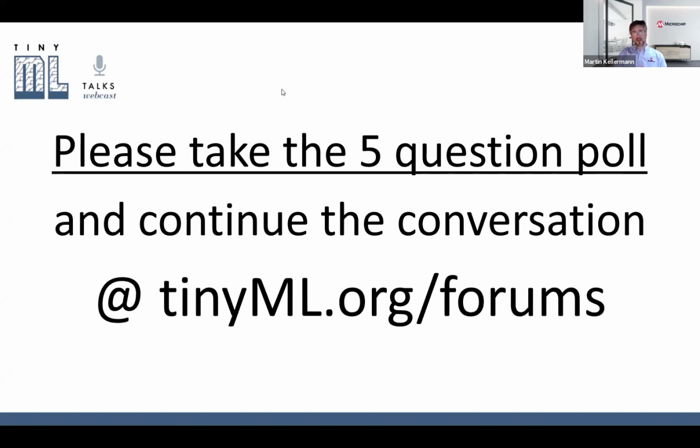So LegUp HLS does exactly that one, and I didn't really want to create the network myself. I didn't want to try to hand optimize the C code into VHDL, but I left it to the tools. And Infxl provides different ways how the C code is written, and those have also some implications in the tool. But in general, it doesn't really pay off to have manual work put in here. It's pretty good to work with the pragmas and rely on the tool to get a small network.